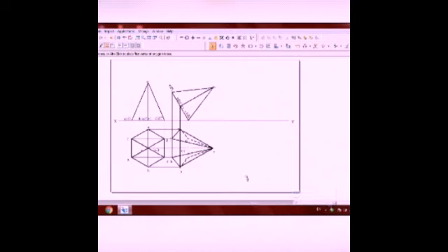At any convenient distance, draw a 30-degree line. Of course, remember that the 30-degree reference line need not touch the XY line. Draw any other reference line, and for that reference line, draw the 30-degree line. Since you drew the reference line parallel to the XY line, the line that you are drawing will be 30 degrees to the XY line. Of course, you can check that 30 degrees by measuring the angle or marking the angle. There you have to mark the angle 30 degrees, and then